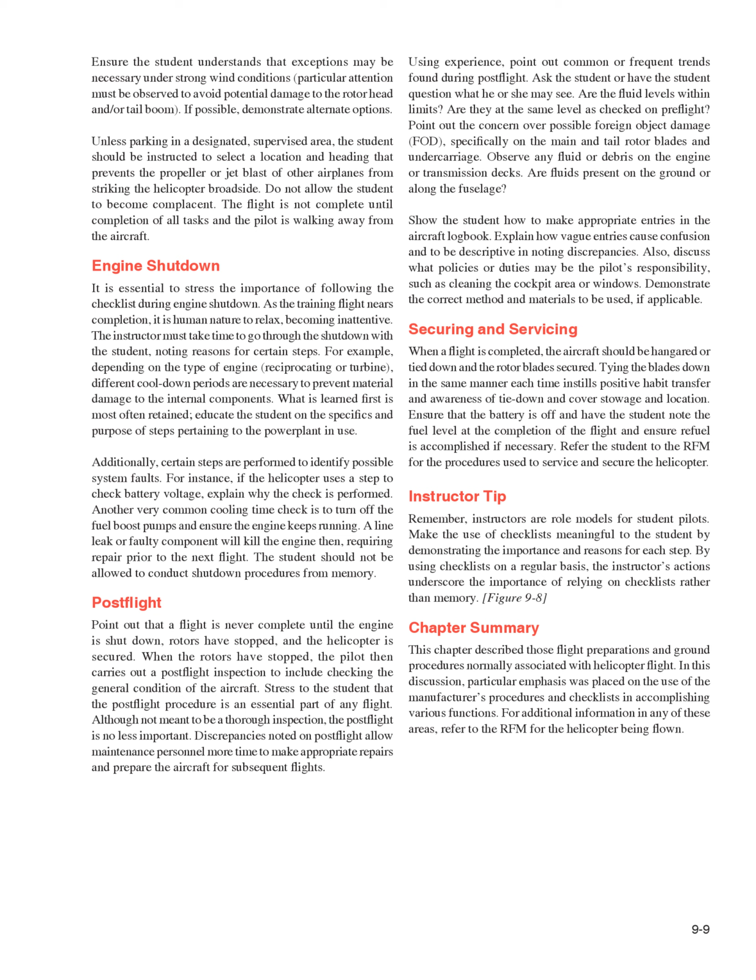Post-flight. Point out that a flight is never complete until the engine is shut down, rotors have stopped, and the helicopter is secured. When the rotors have stopped, the pilot then carries out a post-flight inspection to include checking the general condition of the aircraft. Stress to the student that the post-flight procedure is an essential part of any flight. Although not meant to be a thorough inspection, the post-flight is no less important. Discrepancies noted on post-flight allow maintenance personnel more time to make appropriate repairs and prepare the aircraft for subsequent flights.